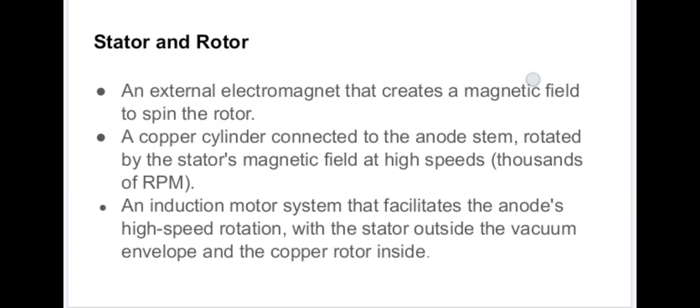X-ray machines are designed so that the tube cannot be energized until the anode attains its full speed. This delay time is incorporated in the exposure button. The power supply to the induction coil will produce eddy currents which cause heating of this rotor assembly.